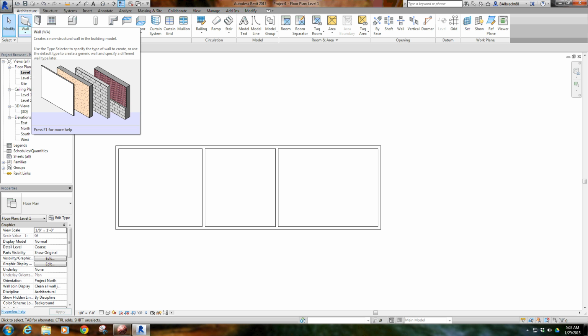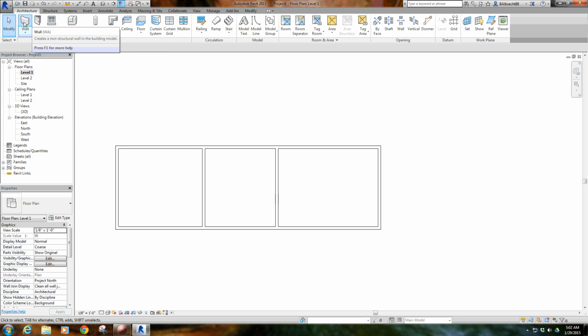And then I'll use some stuff. Some of my hotkeys make no sense based on their tool. Like WA makes sense for a wall, DR makes sense for door. But I might have, trying to think of one that I use a decent amount, like split.